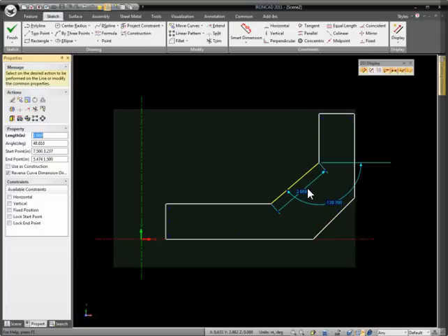The other nice thing with these handles is you can use them to align to other curve elements. For example, how do you know which end of the curve is going to move when I drag this point? It's going to tell you based on the length arrow. If I move this point, this is the end that's going to move. For example, we can see that top element moves. If I switch the curve to the other side, when I drag this element, that end of the curve will be the one that's adjusting. So it's really handy to be able to understand which one's moving. And again, we can move these down.